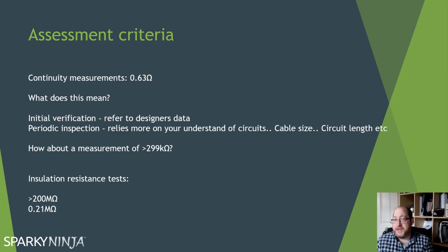If your instrument is saying greater than 299,000 ohms, it's likely that you've got an open circuit between the 2 points of your measurement.